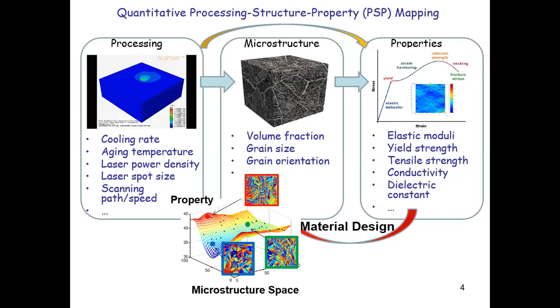And you can see from this feedback loop that a key thing is you have to know what happens during the processing, right? When you heat up the material and cool it down, what's going to happen in the microstructure. Okay, and as we said before, the key things happening in the microstructure are different types of phase transformations, right? You can have large alpha grains, and then if you heat it up and cool it down, you can induce the growth of a secondary phase, like beta grains within the alpha grain. How it grows, how fast it grows, how large it can grow, how these are related to the processing temperature, etc. And this is important. So that's going to be the main topic of our class.